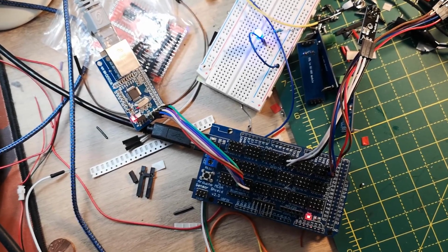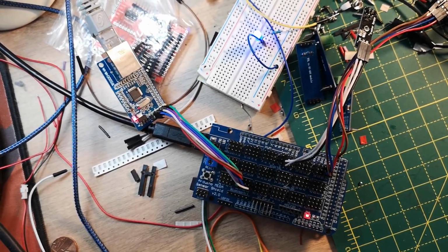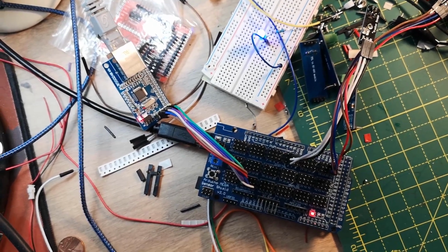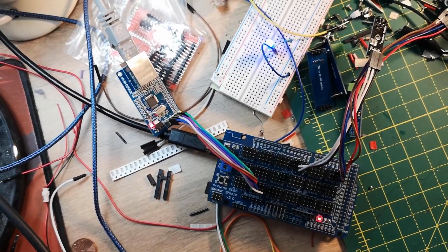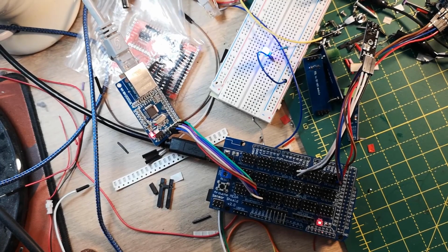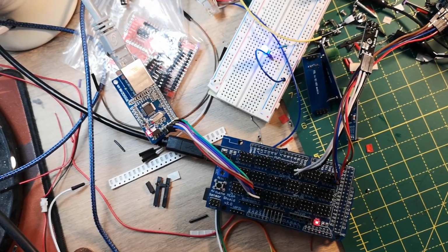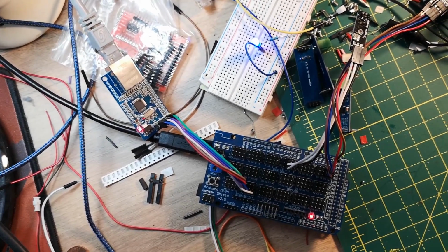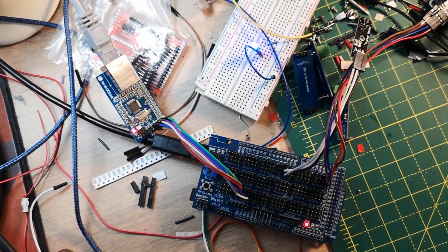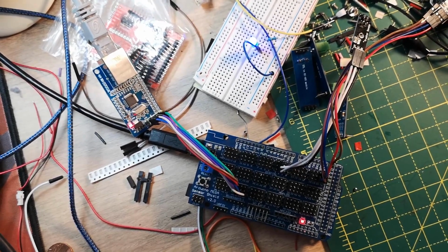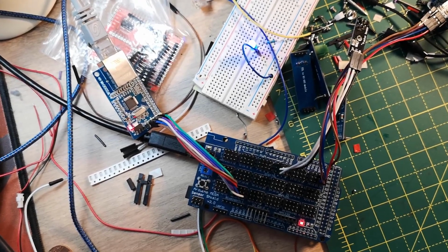If I do get MQTT working acceptably up there, how am I going to shift all existing accessories onto MQTT? Also, Ethernet for me is very useful, but it still means dragging lots of wires around. So Ethernet and Wi-Fi both sit on TCP/IP, which is kind of what I'm implementing here anyway. So another thing to look at would be how reliable will this be over Wi-Fi? Can I get rid of wires altogether? So still lots of things to look at, but I'm going to keep plugging away at it because I think there really is some value in this.